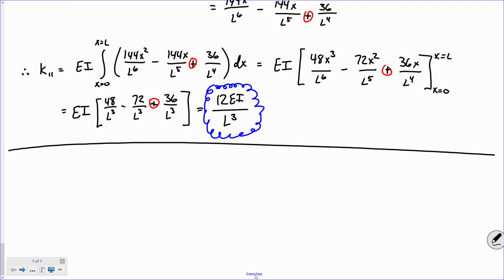Okay. Now, all this stuff that we did before was to try and do the finite element derivation of a stiffness matrix. Now, in finite element analysis, you're solving for the unknown displacements. But to solve for the unknown displacements, you need two things. You need stiffness matrices and what? You need loads. You need force vectors or load vectors. So what I want to do is go back and look at load vectors. And this will be quick.